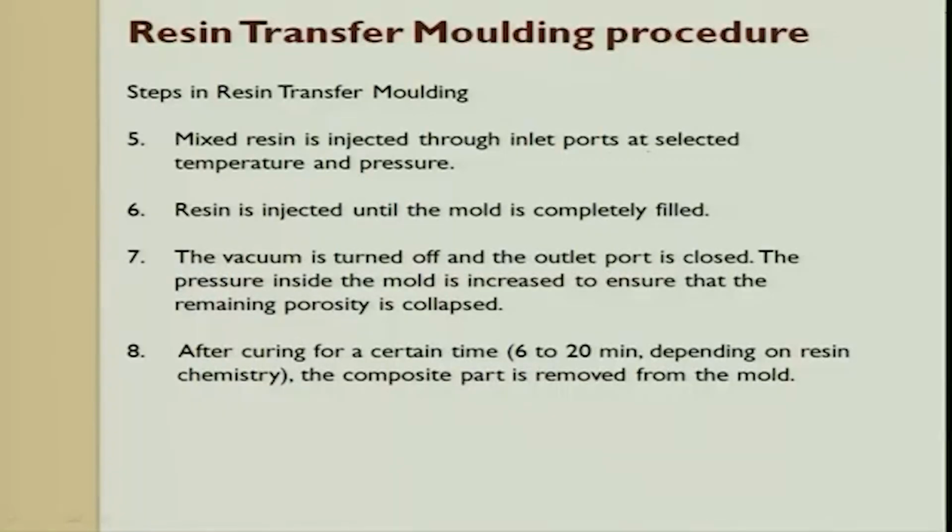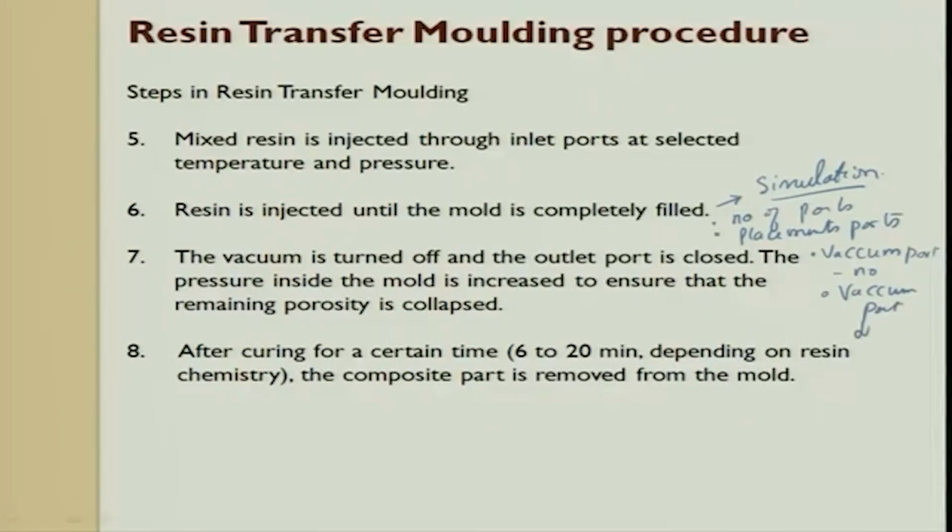The resin is injected until the mold filling is complete. This is a challenge. So, there are a lot of simulation softwares available today to tell us the number of ports, placement of ports, all these things. So, here placement, number, and then we also see what vacuum you have to apply, vacuum port number, then vacuum port location. All these things, today there is software wherein people use simulation, try to find out different locations and then only they do it, because it is a costly affair.